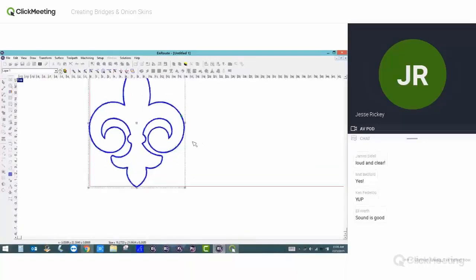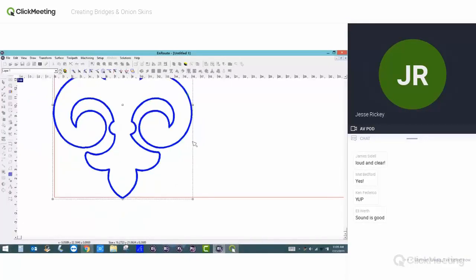And the benefit of that is now this bridge becomes bigger and this one stays the same. This is still a 1/2 inch. Now this is 1 inch. So if there's different places I need to do different sizes, I kind of use the 80-20 rule. When I'm setting up my parameters the first time, I will do it for the majority of the work, and then I can come back and edit them simply by right-clicking in that bridge.